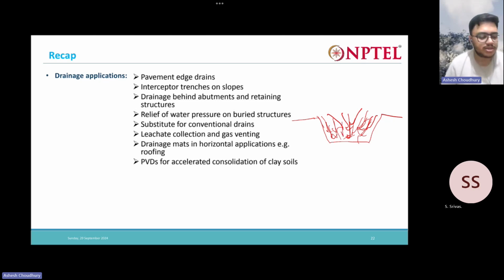There are engineered and non-engineered landfills; both exist. Many years back, 50 or 100 years ago, most were non-engineered landfills, but nowadays most of the landfills are engineered. That means you have a lining made up of a geosynthetic clay liner or geomembranes. Those linings prevent the passage of harmful chemicals, or chemical action, rapid decomposition and so on, so it does not come out.